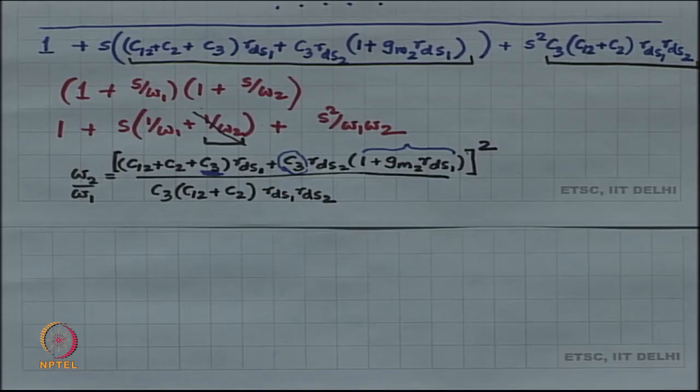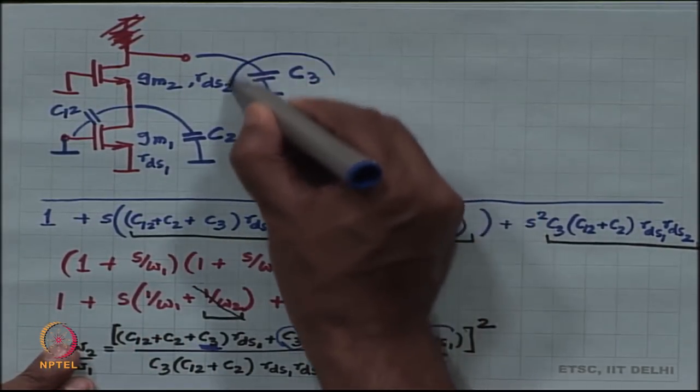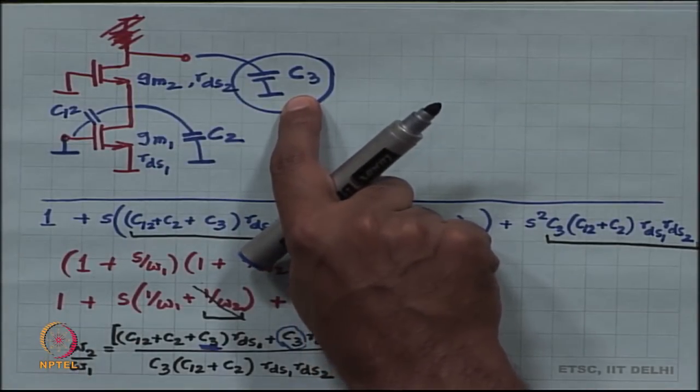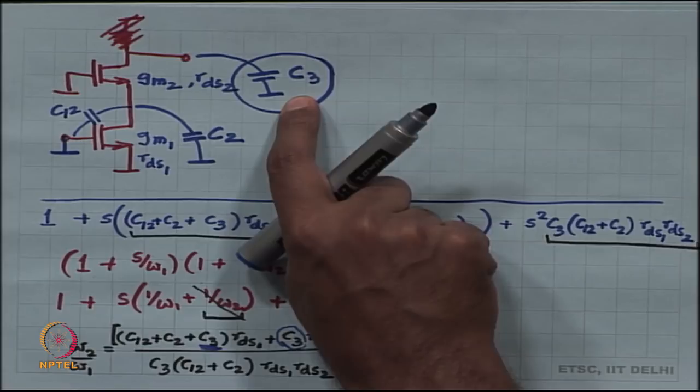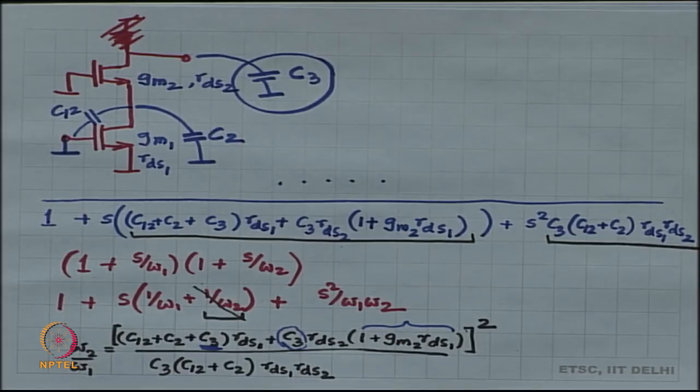Fine. So, this is going to be the compensation technique. The compensation technique is going to be to add capacitance out here, right, at the load. At the load we just dial in more and more and more capacitance till the requirement of phase margin is met, is satisfied. All right.